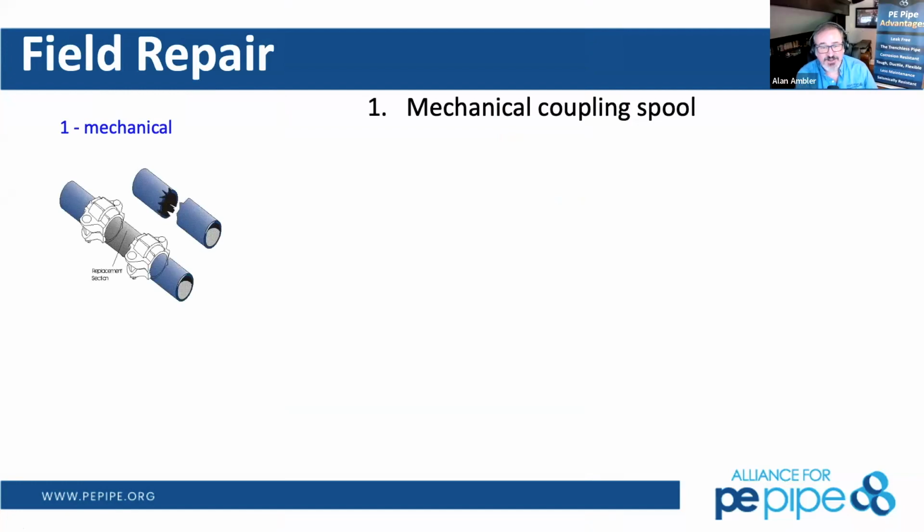So some of the development of these tests, everybody out there, came from doing the fusion the right way and doing the fusion the wrong way, so we could test whether or not the actual fusion worked. So the operator performing that electrofusion would subsequently not prepare the pipe in the appropriate manner, study how it failed, and then also be able to recreate that routinely.